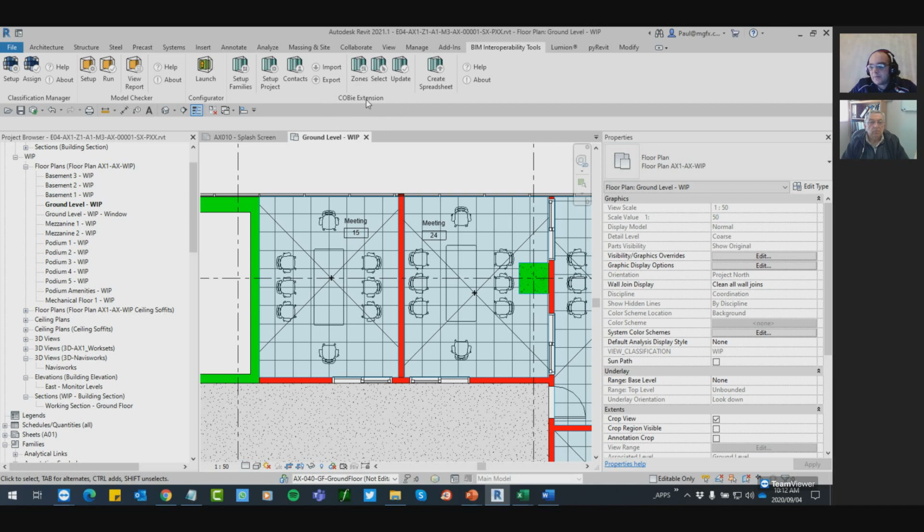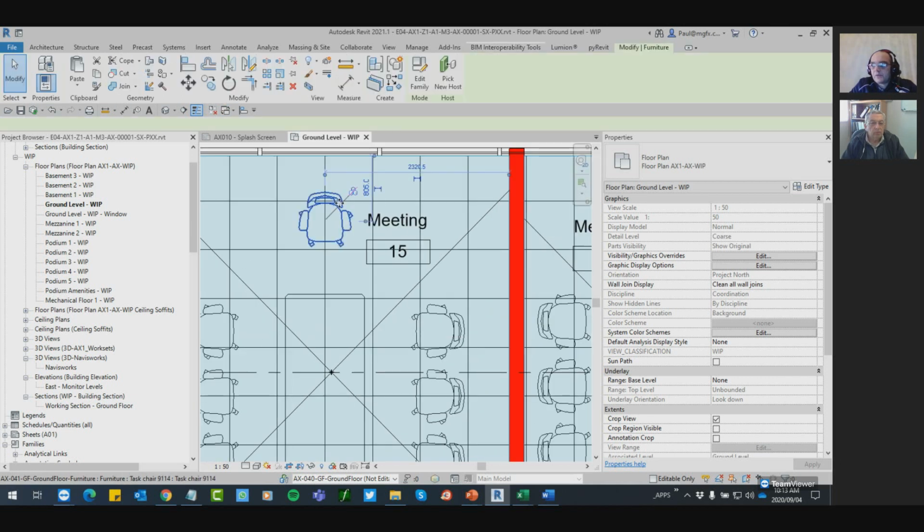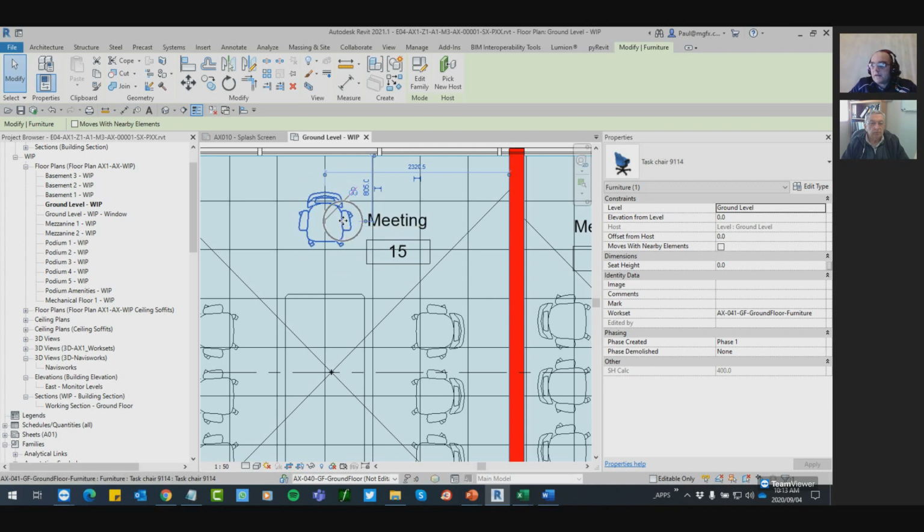So once the contractor has built the building, then it will be managed through the COBie parameters. It's written out into a spreadsheet, and that spreadsheet is then used for facilities management. Its origin is in the United States, but it's been adopted by the UK, and it's applied across the Middle East as well. The classification manager has fewer parameters. It's simply going to say, and I'll give you an example of what you might be familiar with.